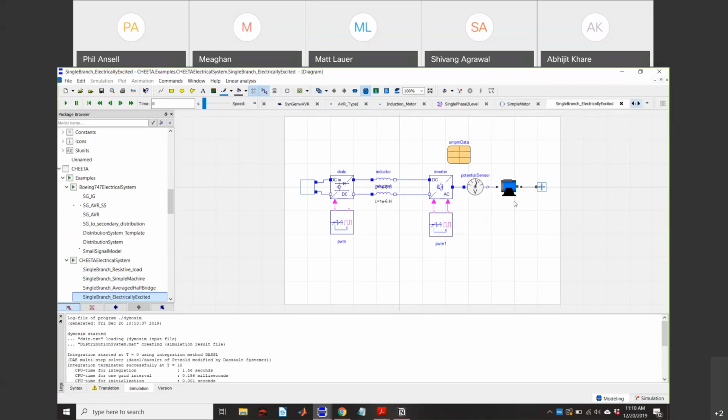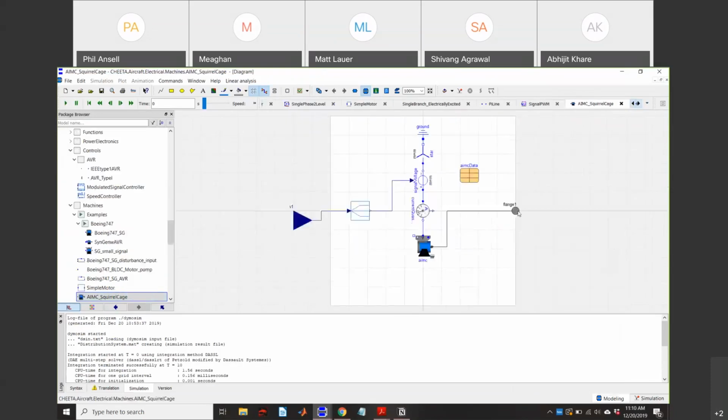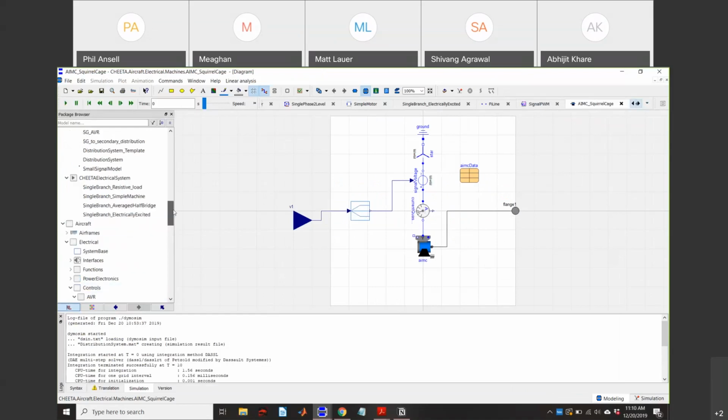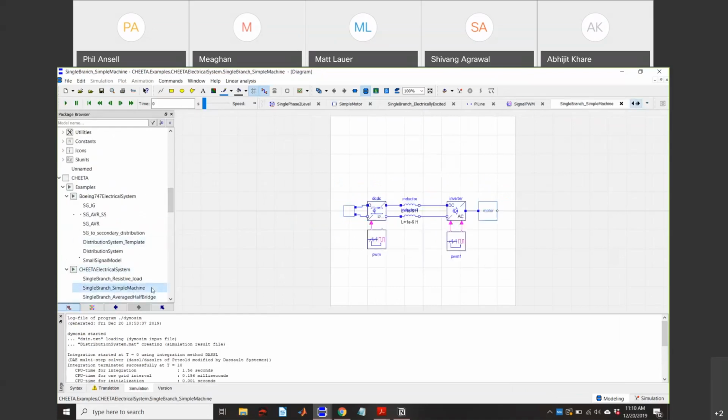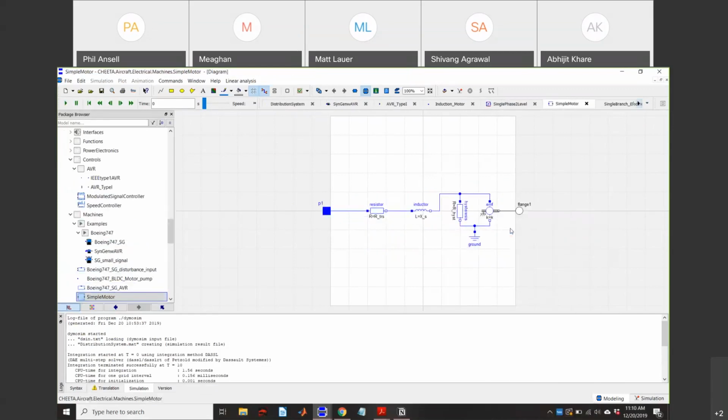And then on the right side, when we're moving up to a more complex motor model, we'll have a sensor reading into our induction motor model and being able to provide a signal voltage for that. And that will produce a mechanical signal to drive our fan. But in the more simple motor system, we will have just the inverter directly electrically connecting to the motor. And inside of the motor, we will move to the mechanical domain via using an EMF. And the EMF will then drive the fan itself.